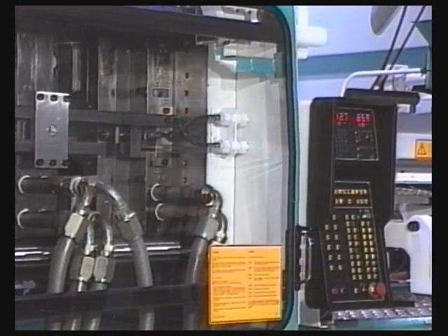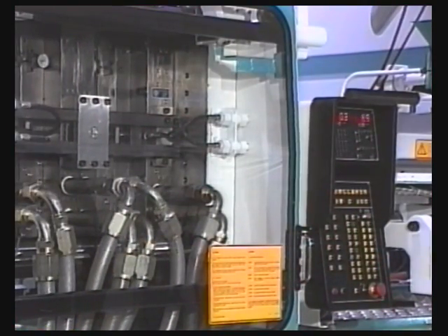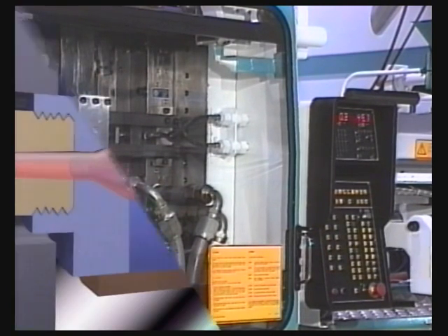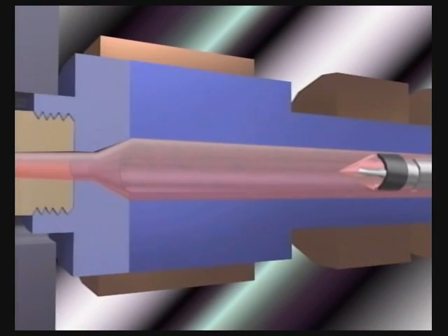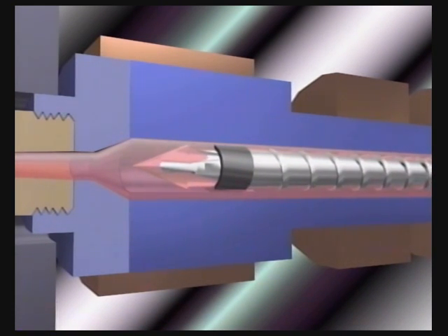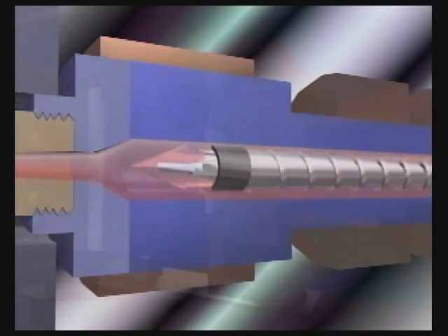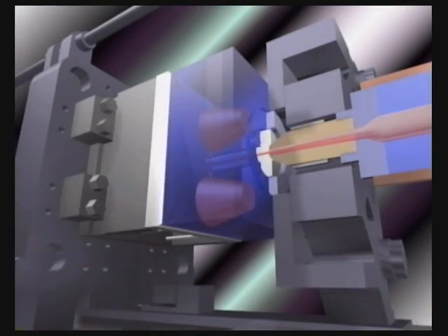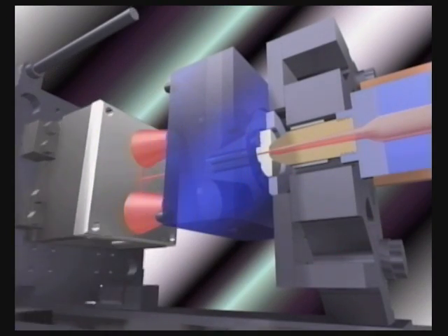More advanced machines can control multiple stages of injection velocity. For example, a process may demand a slow speed to fill the sprue and runner, a faster speed to fill the part, and a slower speed just before the part is completely filled. Later model molding machines allow for better control of the process, and as a result, yield less part-to-part variation and better part performance.